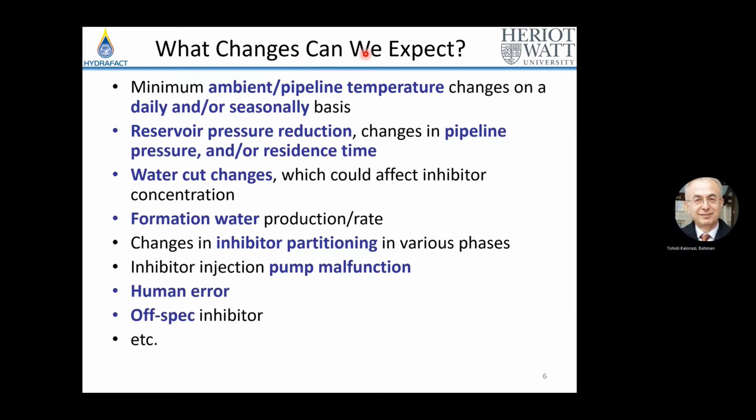So in the life of a reservoir, what changes can we expect? It's possible that in the life of the reservoir, or even daily, the minimum ambient and pipeline temperature changes. If that changes, it means you need more or less inhibitor.